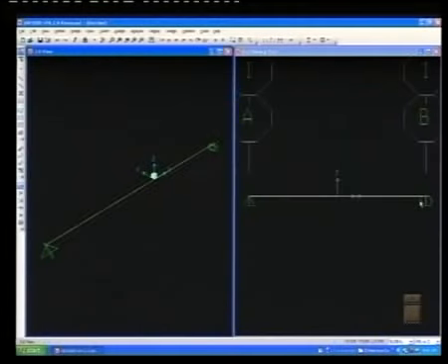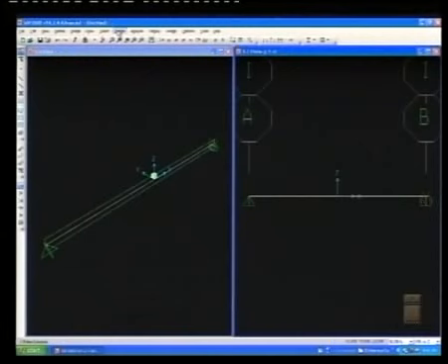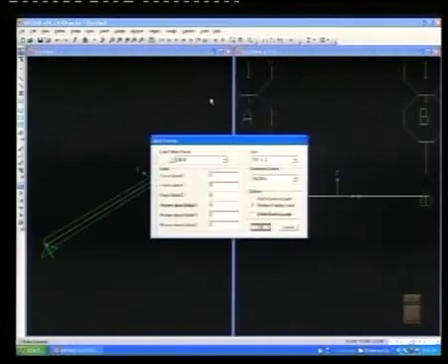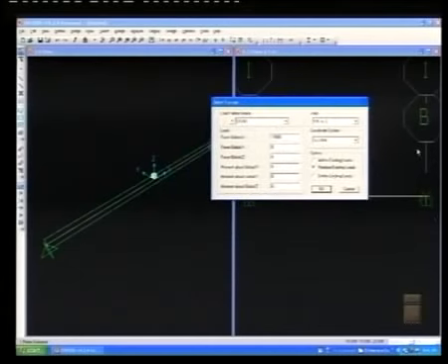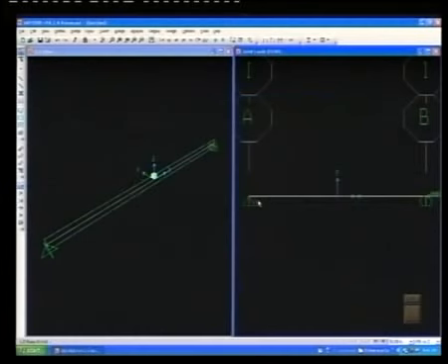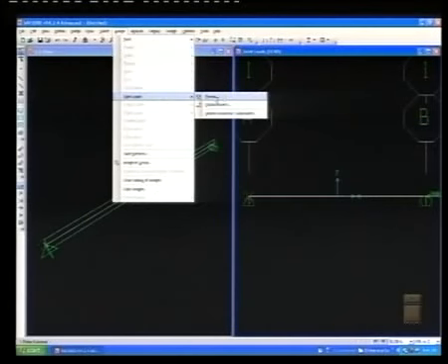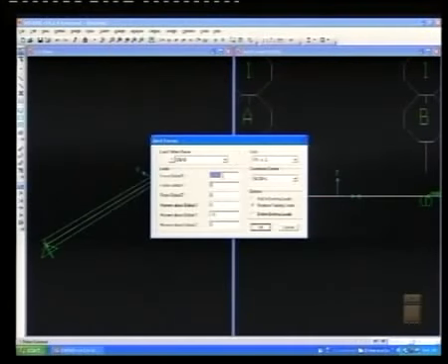Now if we want to put the bending moments, then we say that here we have assign joint loads, forces. We make it on the dead load case and we put the dead equal to 0. We have minus 1,800 kilonewton. And notice that the bending moment at this end, to be in this direction, it is in the negative y direction. So we said minus 70. This is okay. On the other side here, we put assign joint loads, forces, and here it is 0, but at this end it is plus 70.